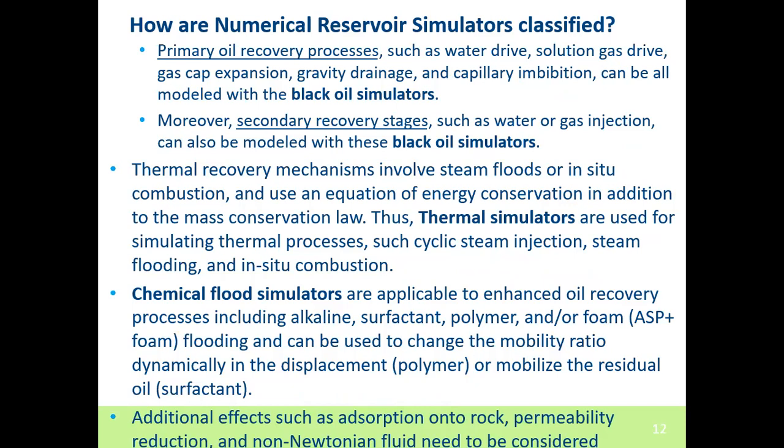For thermal recovery mechanisms, which involve steam floods and in situ combustion, an equation of energy conservation will need to be added, and therefore you will need thermal simulators. Thermal simulators are used for simulating these processes. If you want to capture chemical enhanced recovery, you will need to use a chemical flood simulator.